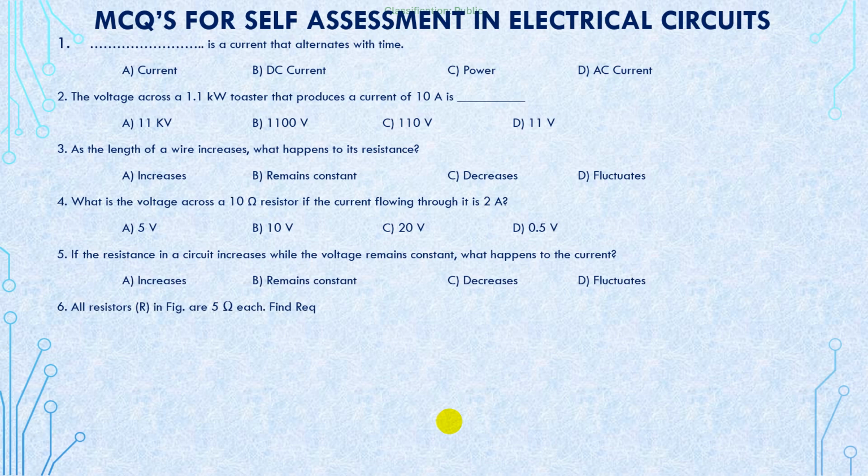Now in the figure, all resistances are 5 ohms, then find the R equivalent. Now you have to check it. So this is your figure. We have 6 resistances here. By seeing from this end, what is the equivalent resistance? You have to solve step by step. We can draw new circuits also, so that you can easily get the result. First you solve these two. They are in series, so 5 plus 5, all are 5, so 10 ohms. Then these two come to 10 ohms and become parallel with 5 ohms.